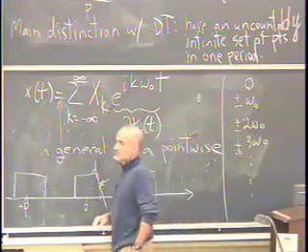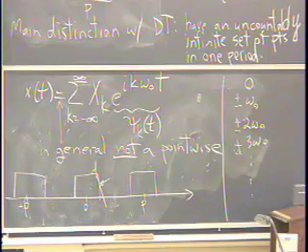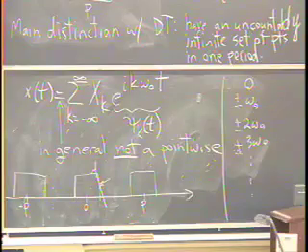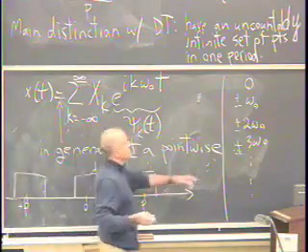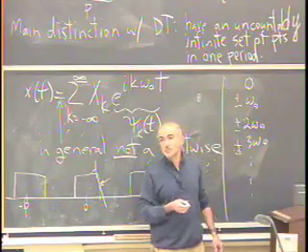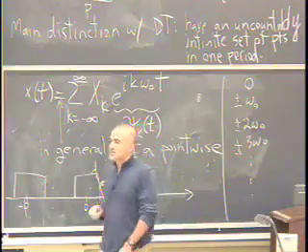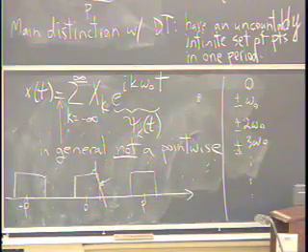Okay? So if I'm looking at a periodic signal of period P, there's no way that's going to have any frequency component at frequency, say, omega naught over 2, or 3 omega naught over 2. The only frequencies that can contribute to that signal are these integer multiples of the fundamental frequency.